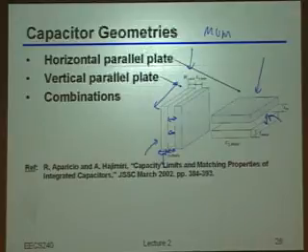You can actually leverage the fact you have many metal layers and fill these things vertically with vias and metal layer, via, metal layer, and so on and so forth. Again, we'll see a picture of that shortly. But the meta point there is indeed that this tends to be the more attractive option in more advanced processes.